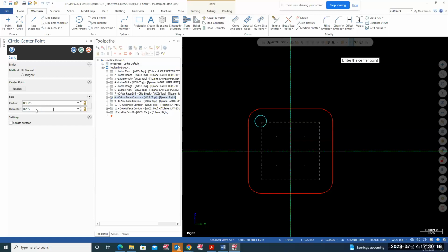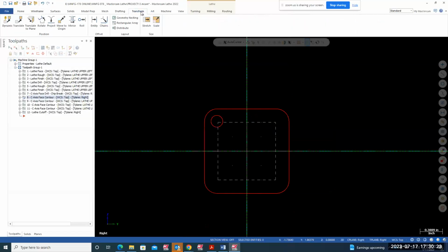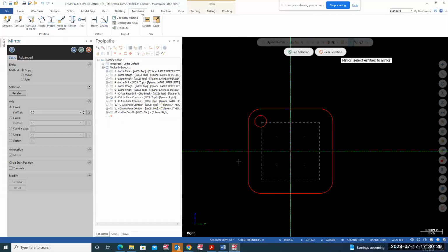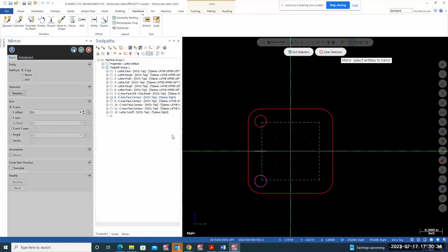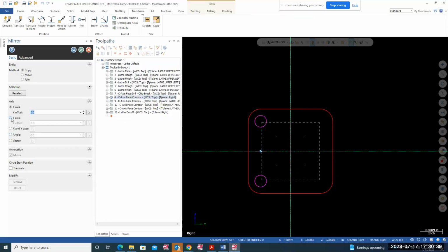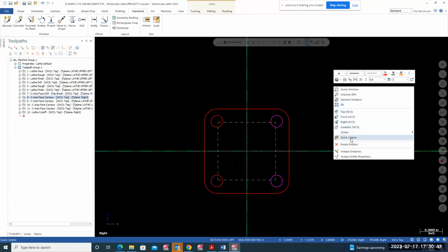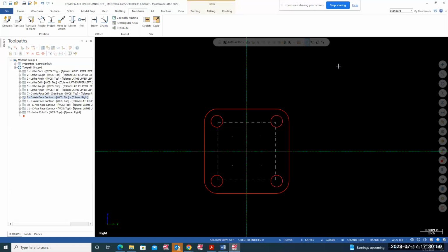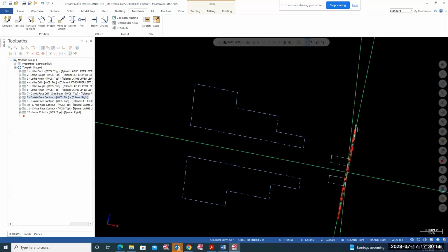And these holes are 205 diameter, 0.205. So that hole, and then I can just go ahead and mirror that hole, transform, mirror this hole to the y-axis, hit OK, then pick this guy and this guy, mirror this to over here. Right click, clear colors. So you have that, and look at this, I'm drawing at Z0, right at Z0 on construction plane right.